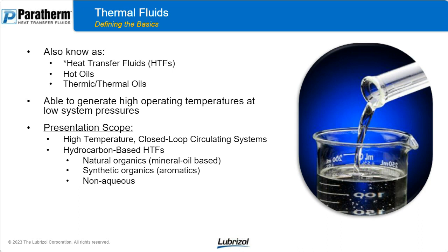The presentation scope, we're going to be limiting this today just because of the limited time we have, and we can't go into an overall scope of all the different kinds of fluids that might be present. We're going to focus on high temperature systems that operate in a closed loop. And by closed loop, I mean that they have a closed loop with an open vented expansion tank, but the loop itself is not an open bath. It's not open to the atmosphere like that.